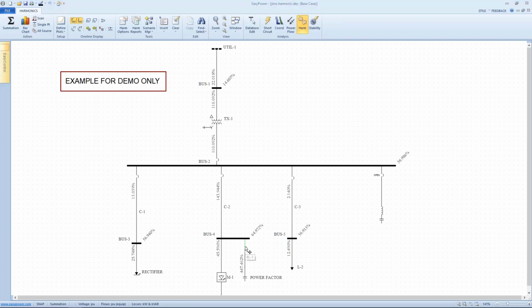So if I take that capacitor out, I can see I'm back down at 13% harmonic distribution for current, 13% harmonic distribution for voltage. Still exceeds my 5% goal, but it's better than when that power factor correction was in place.